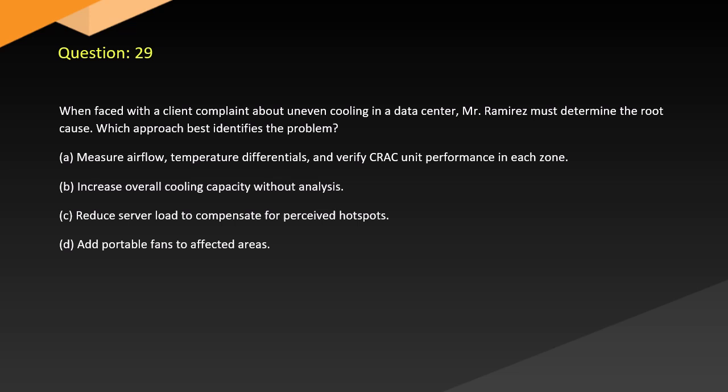Question 29. When faced with a client complaint about uneven cooling in a data center, Mr. Ramirez must determine the root cause. Which approach best identifies the problem? A. Measure airflow, temperature differentials, and verify CRAC unit performance in each zone. B. Increase overall cooling capacity without analysis. C. Reduce server load to compensate for perceived hotspots. D. Add portable fans to affected areas.